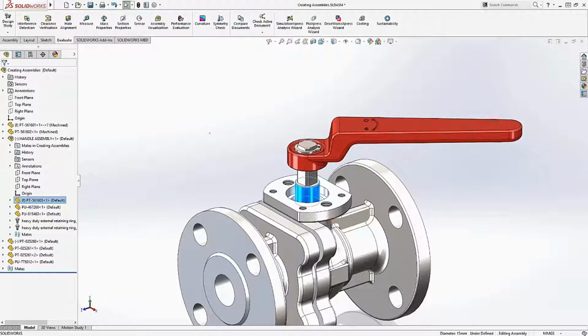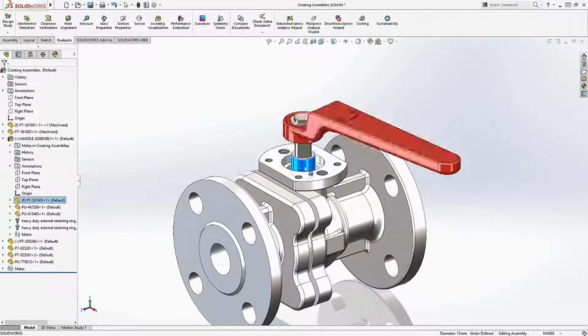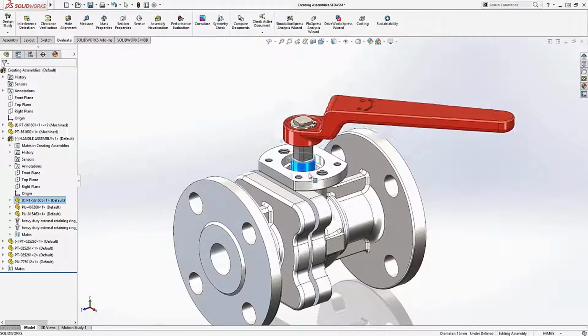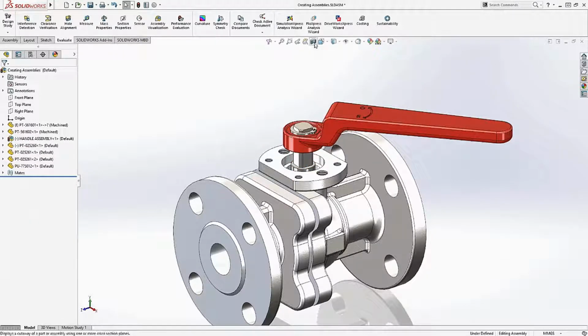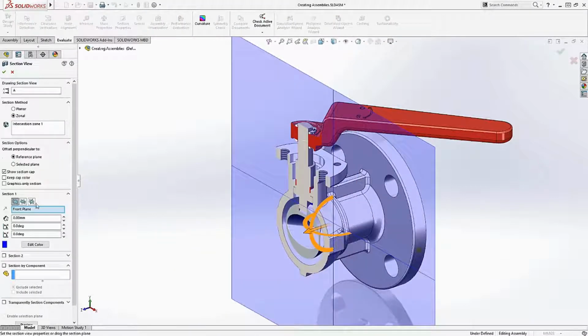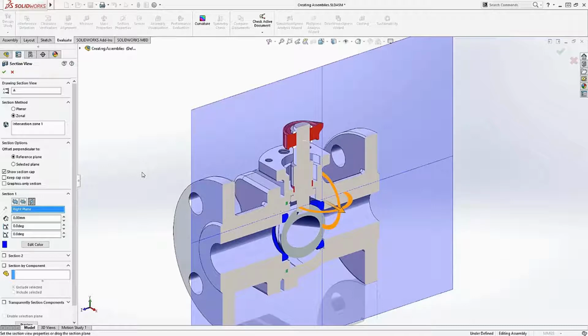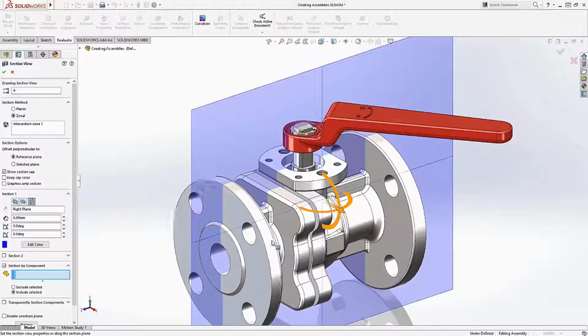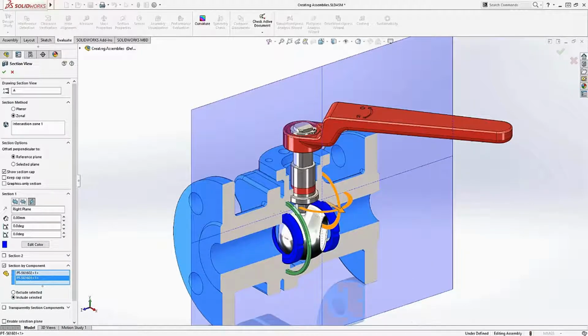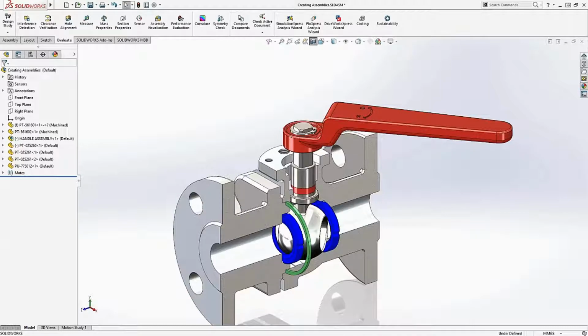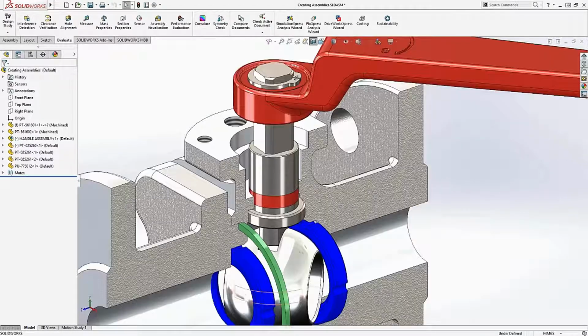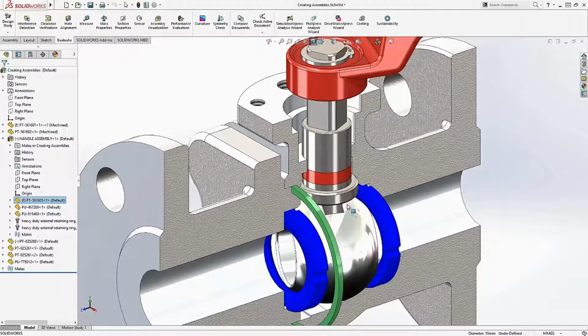Now you'll notice that when we put the geometry together, we're not just placing it. It also contains movement inside. And in this case, this part's free to move up and down. This is a great place where a section view could really come in handy. Now I'm not talking about section views as they relate to a drawing or documentation. We use section views in 3D to get a better understanding of how our components look and the ability to see inside of them. And in this case, I'm going to choose the option to only section the components that I select. So when I do this, you'll notice that I've sectioned the two housings, but I'm still able to move and interact with all the other components.